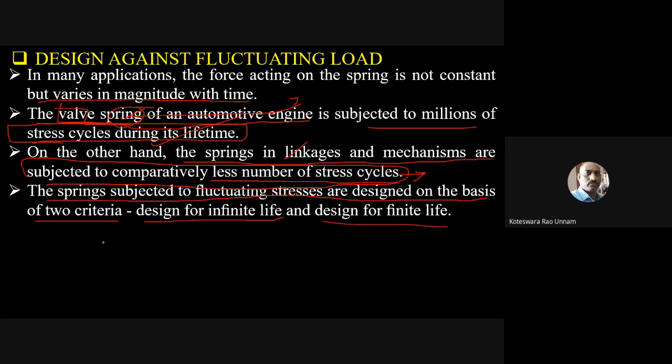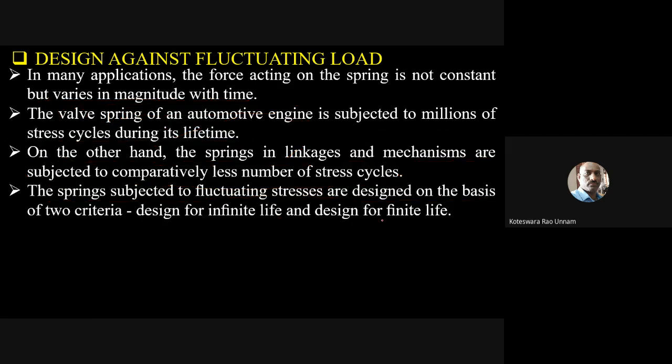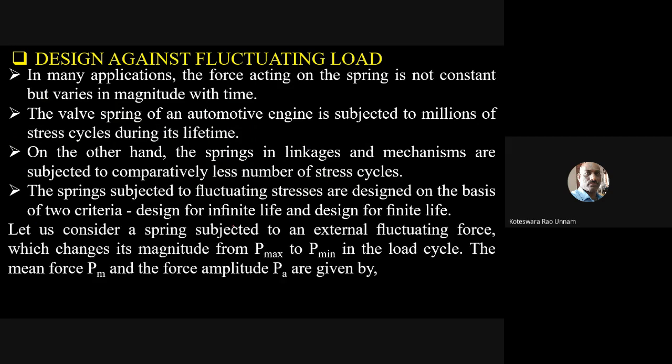That depends upon the application. For valve applications, design for infinite life; for fewer stress cycles, design for finite life. Then we will see what equations we need to use to design the spring for either finite life or infinite life.